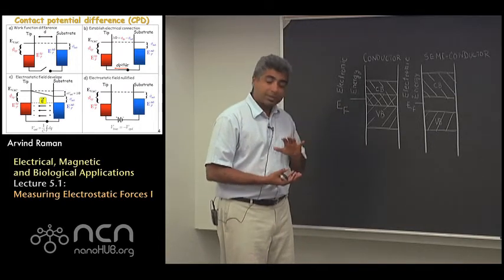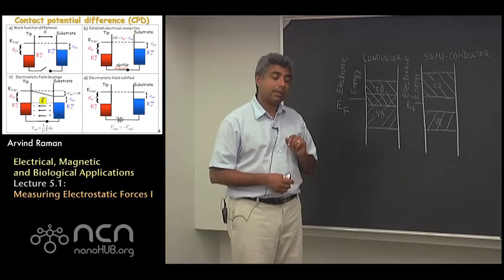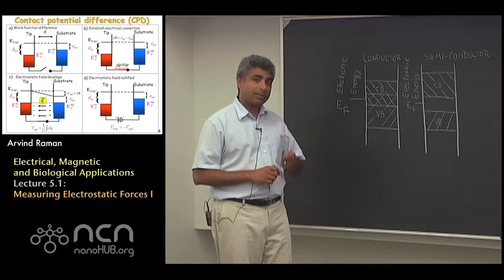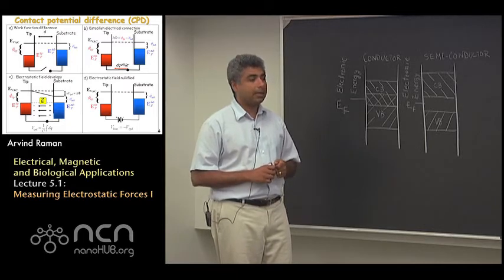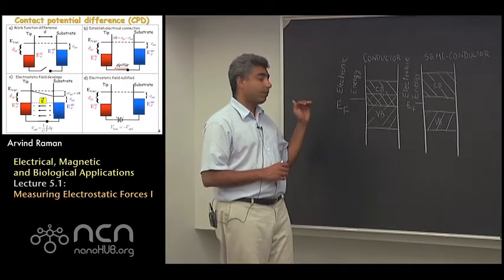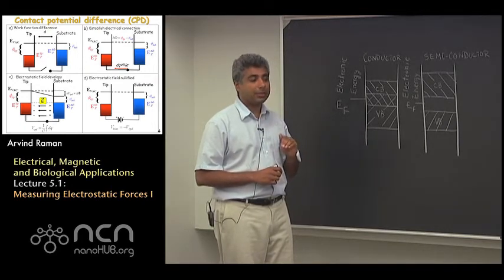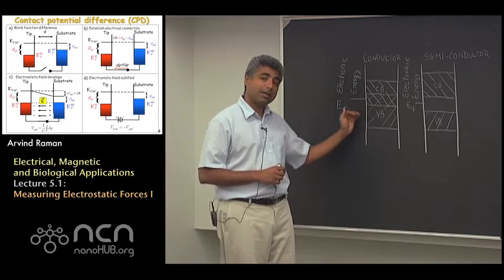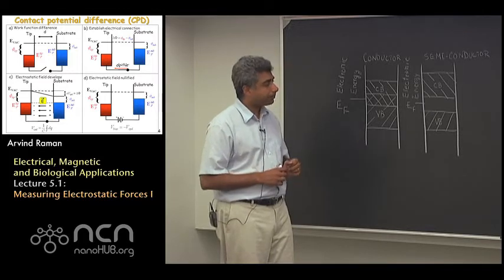Now, the band structure just tells us about the possible energy states that electrons can sit in, or the allowable states they can sit in within a solid. To really understand which of the states are actually occupied at room temperature, one needs to go to Fermi-Dirac statistics, which roughly tells us that for each conductor there is an intrinsic Fermi level, which tells us the energy level below which most of the states are actually occupied by electrons, and above the Fermi level, the states are actually not occupied.